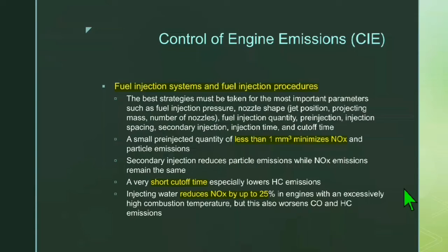A small pre-injected quantity of less than 1 mm³ minimizes NOx and particle emissions. Secondary injection reduces particle emissions while NOx emissions remain the same. A very short cutoff time especially lowers hydrocarbon emissions. Injecting water reduces NOx by up to 25% in engines with an excessively high combustion temperature, but this also worsens carbon monoxide and hydrocarbon emissions.